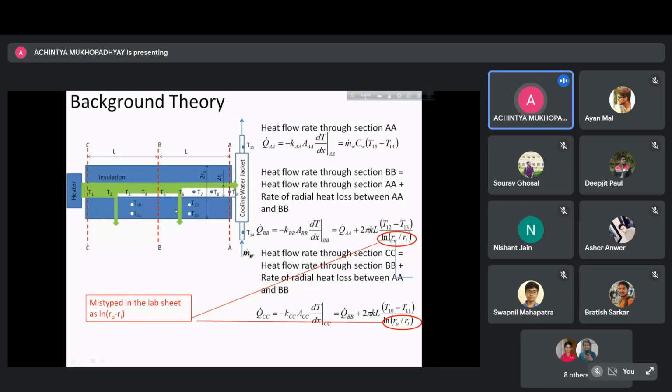Radial, that is fine. But even in our fin analysis, we assume the heat transfer to be just one-dimensional radial at the fin surface when we say that it is only lost by convection to the surroundings. But if the temperatures at these different locations differ inside the insulation, then to calculate the amount of heat loss, you would have to measure the temperature at different locations and do a numerical integration, right?